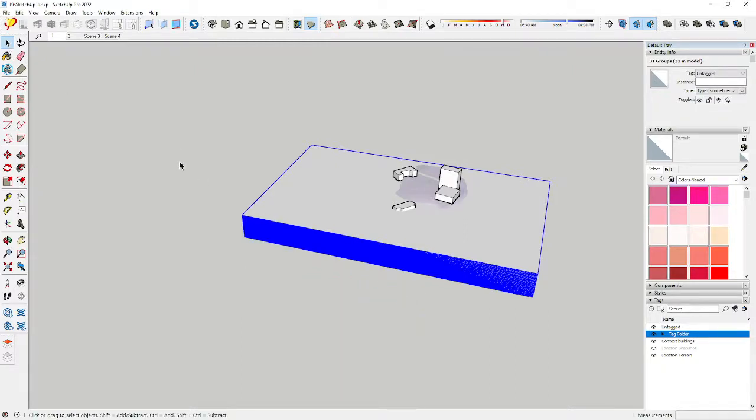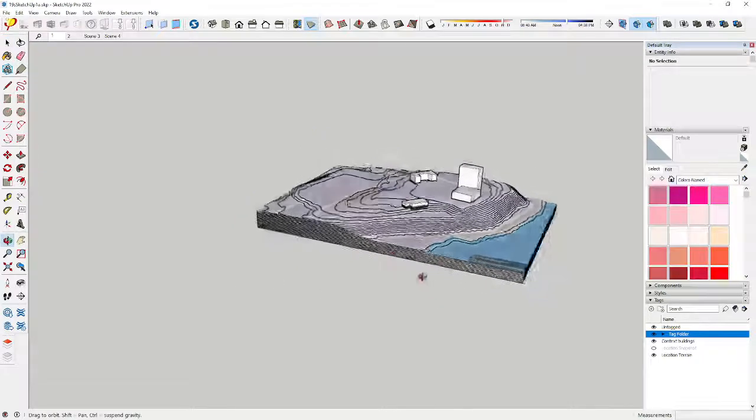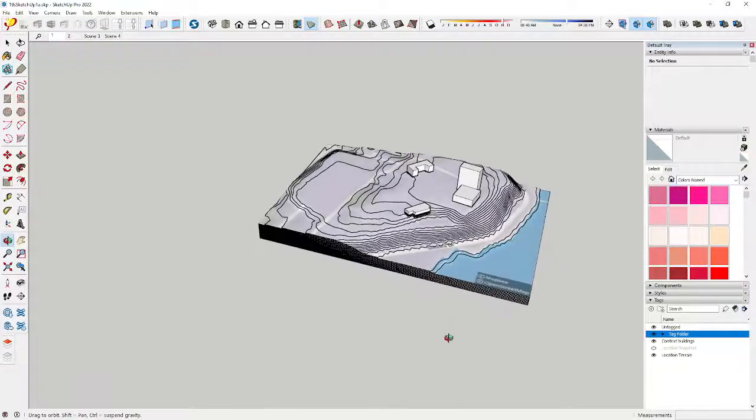and it may not look like anything's happened. Oh, but okay, so it's still doing it. Then what I'm doing here, by the way, why did I do this? I'm cutting contour lines through our model. So if I now select these, I'm making sure I'm not selecting the model inside there. If I did, I would see that this stuff had that surface there. If you do, just Control Z back. If you delete things you don't want to delete, I'm now deleting those surfaces, and you see now I have contour lines. So it's a very easy way of doing it.